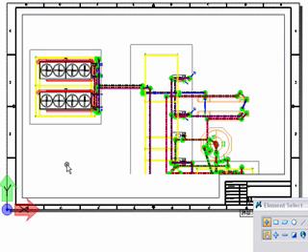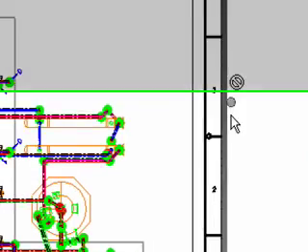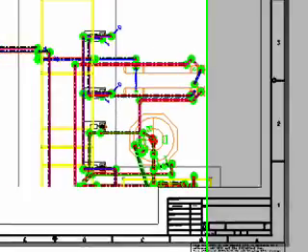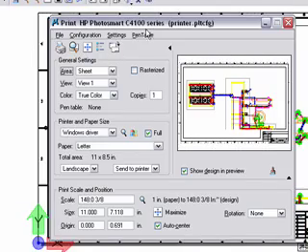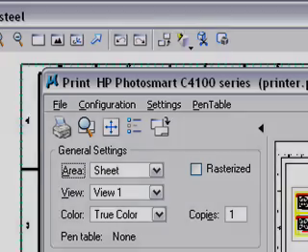Previously, when I created this sheet, you'll notice that I said I'd talk about the display sheet option. The display sheet option is very simply this shadow, this three-dimensional shadow effect around the sheet. So when I come to print this sheet out, you can see straight away that my print area has automatically gone to sheet. It recognizes the sheet. It will only print the extents of the sheet, so you don't have to worry about sizes or doing any other further steps. Just say now,